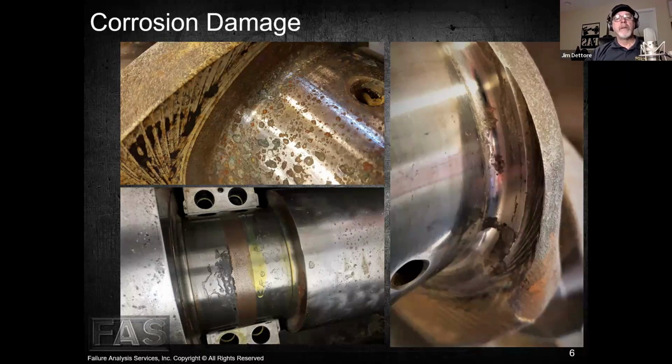If it gets into bearings or into divider blocks, is it going to cause things to want to stick or wear at an accelerated rate? As well, when we have this rough surface against that soft bearing surface, we start to generate very aggressive two-body abrasive wear, or accelerated two-body abrasive wear, like we talked about in the first podcast.